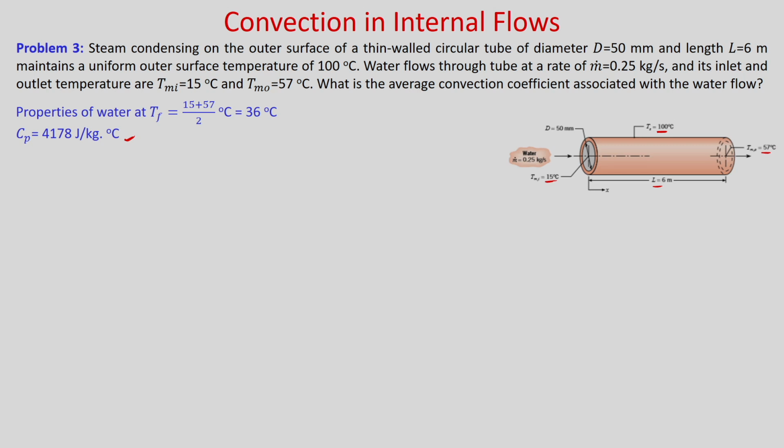Now, we know the heat flux q double prime w as h (Tw minus Tm). We have calculated just now dTm by dx as q double prime w P by m dot Cp.